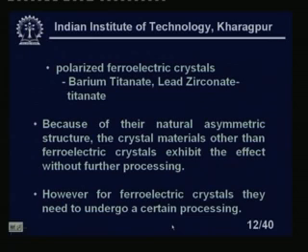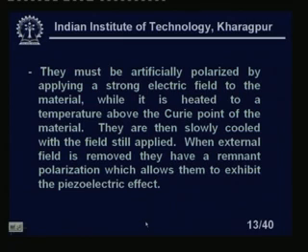However, for ferroelectric crystals, they need to undergo certain processing. What are those? They must be artificially polarized by applying a strong electric field to the material while it is heated to a temperature above the Curie point of the material. They are then slowly cooled with the field still applied. When the external field is removed, they have a remnant polarization which allows them to exhibit the piezoelectric effect. Okay.